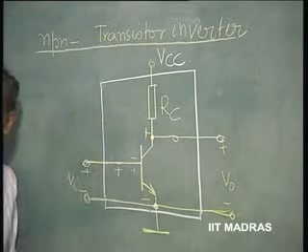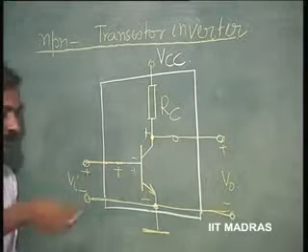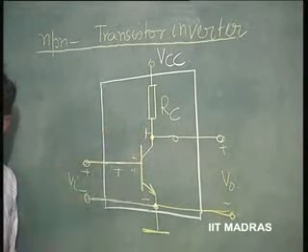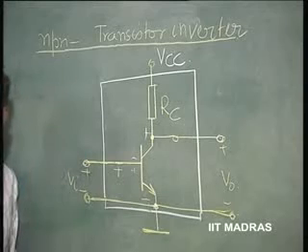The forward bias junction will take a voltage of about 0.5 to 0.6. The rest of it has to come across the collector base junction, which is adequate for reverse biasing it. Okay. So, this is called a single supply biasing of a transistor.